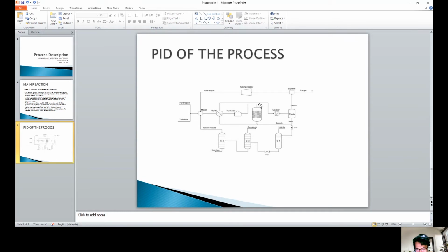So the liquid stream contains benzene and toluene, and also heavy impurities like diphenyl. At the first column, the gaseous components are removed as light. This is followed by the separation of the benzene product in the distillation column C2. On the top of the final column C3, it separates the unreacted toluene for recycling, while at the bottom, the heavy diphenyl will be carried out.